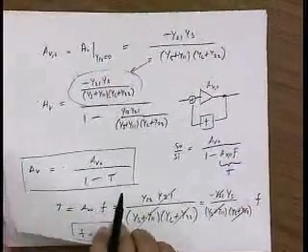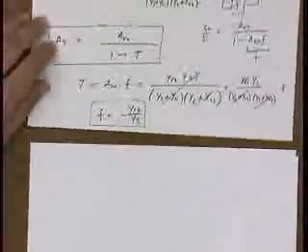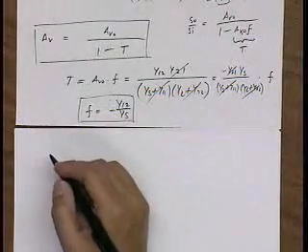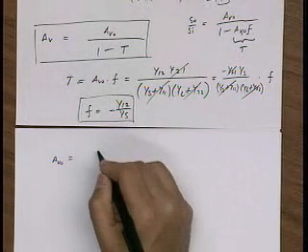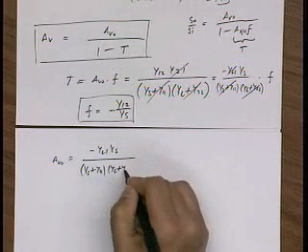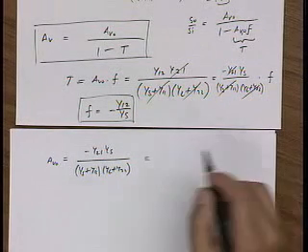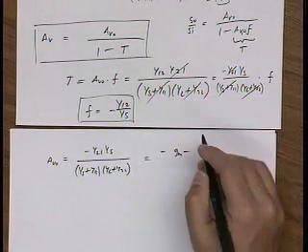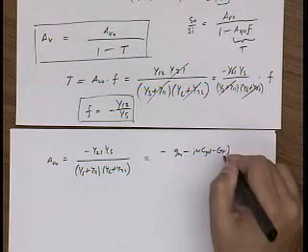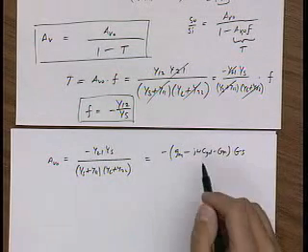All right. Let's plug in some numbers, right? Let's cash in on this calculation. So let's first calculate AV0. AV0 is minus y21 ys over (ys plus y11)(yl plus y22). And what is y21? It's gm minus j omega C gate to drain minus gf. Let's say ys is just gs. Let's say we just drive it with some source resistance.